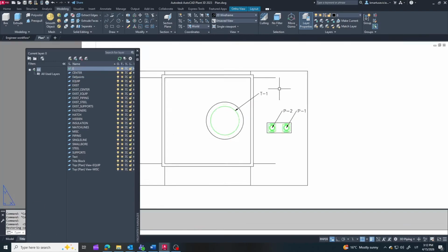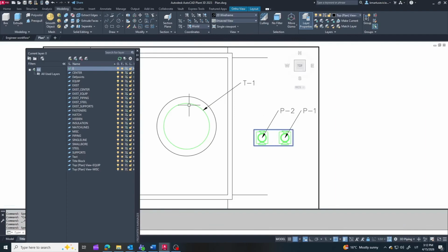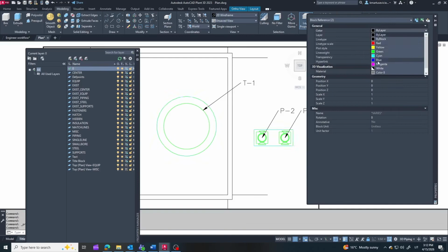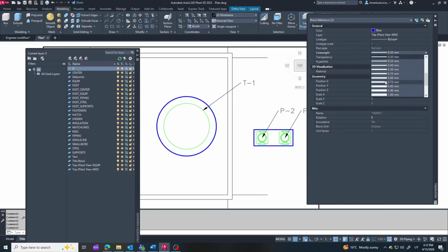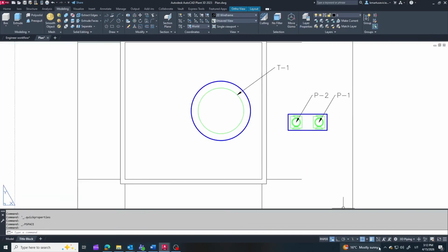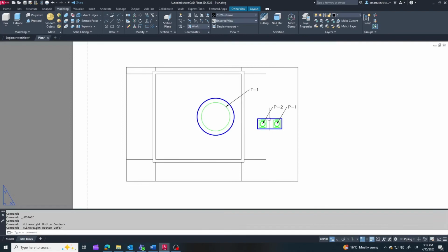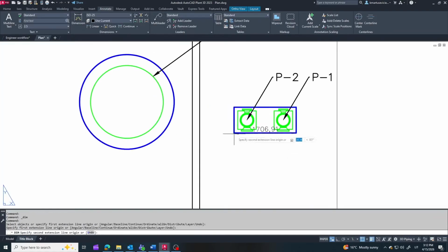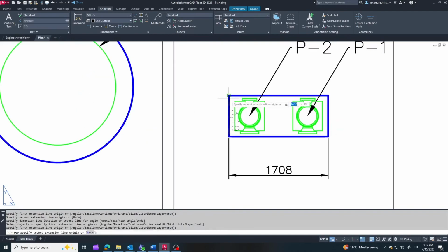Now let's get back from theory to our task for the construction team. I like to clearly highlight the items that need to be calculated by constructors. In our case, these are the foundations for the tank and the pumps. People should clearly see what needs to be done. First of all, dimensions. The dimensions of the equipment itself, and the distances from axes or other reference points.